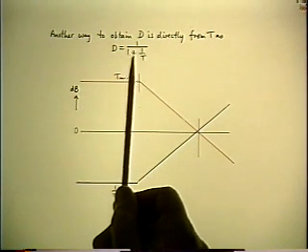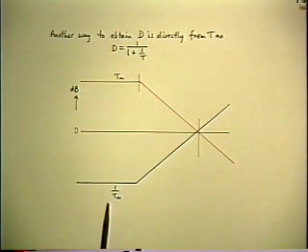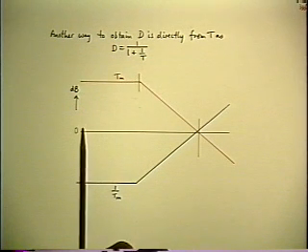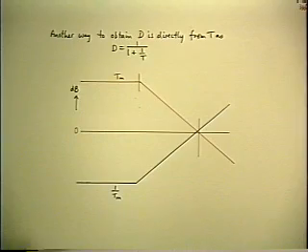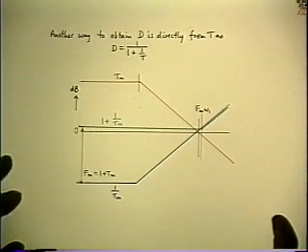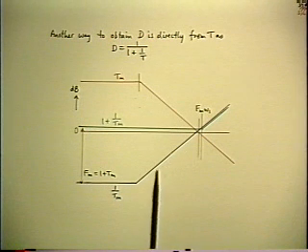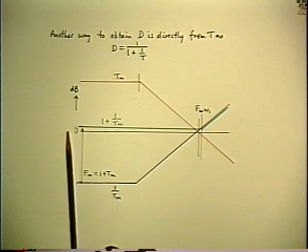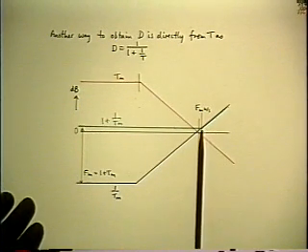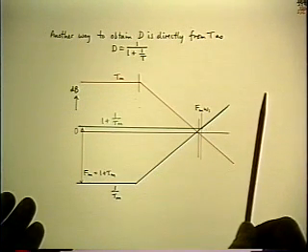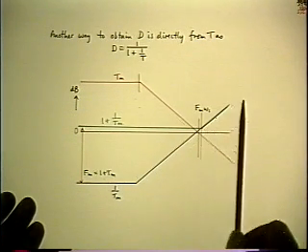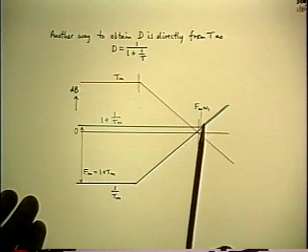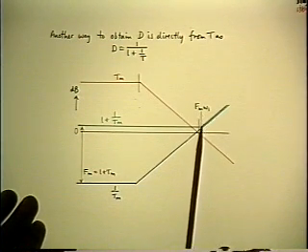The next thing I have to do is add 1. At low frequencies, 1 over T is very small. So when I add 1, the result will be just a little bit bigger than 1, or just a little bit bigger than 0 dB. And as T begins to increase, it still won't be visible. But it'll become visible when 1 over T overtakes 1. Then the sum of the two will turn around and follow the bigger one. And by gain bandwidth trade-off, the value of that frequency, again, is FM times omega 1.